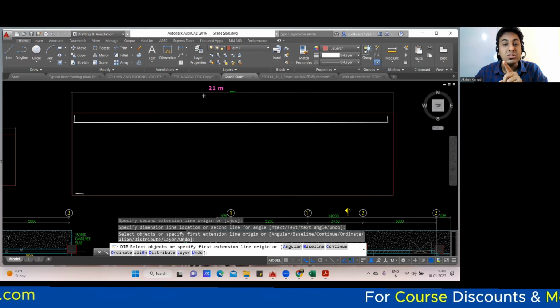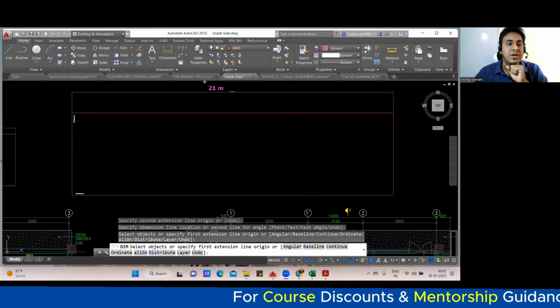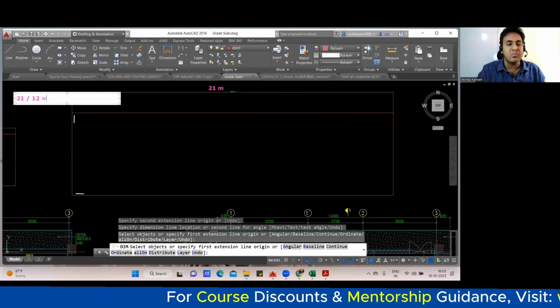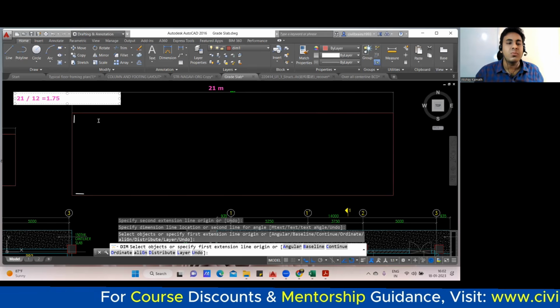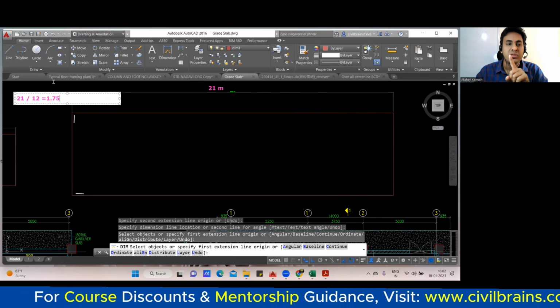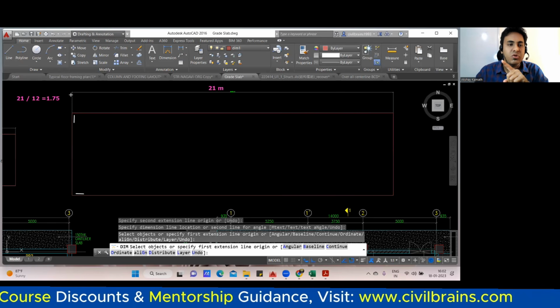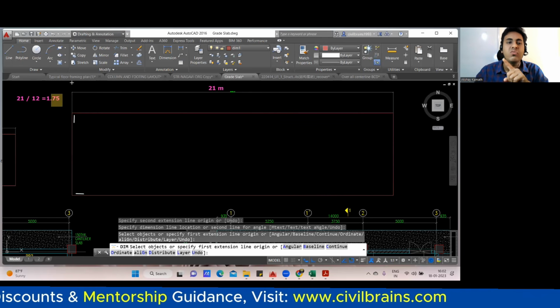But the problem is this is 21 meter. The bar that is available in the market is 12 meter. So what you have to do? Exactly, you have to do the lapping. So how many times lapping will come? That is important. We'll take 21 and divide it by 12. So what is the answer you're getting? 21 divided by 12, you'll get 1.75. Forget about the decimal point. Whenever you find the number of lapping, I always told you to forget the digits after the decimal point. Only the number before that, which is only one. So only one lapping will come.